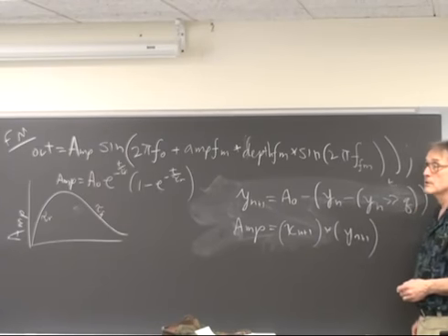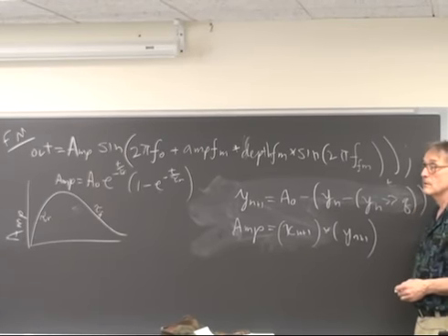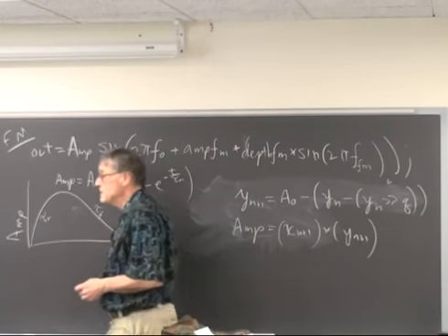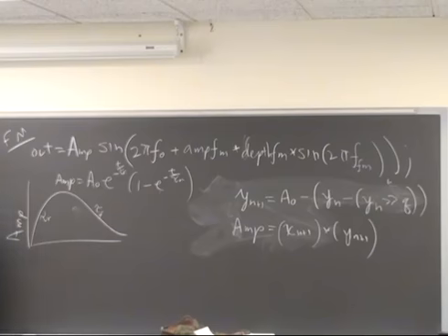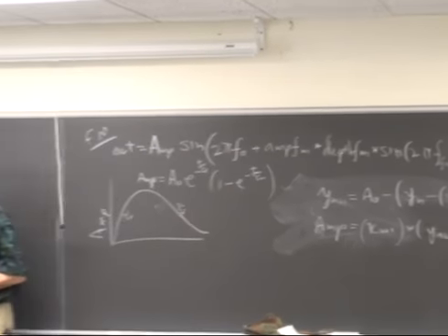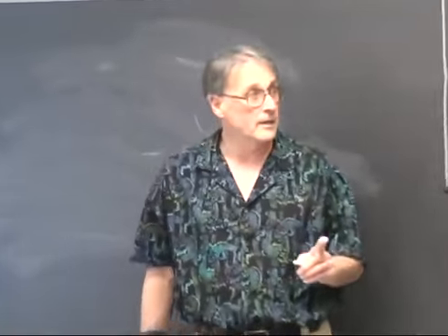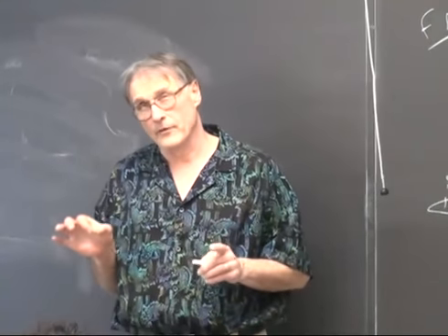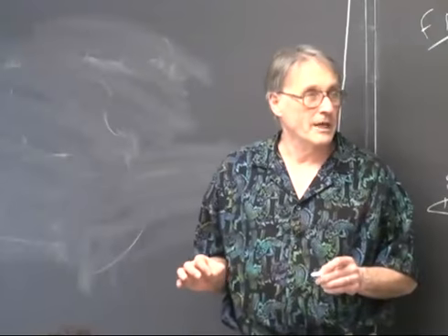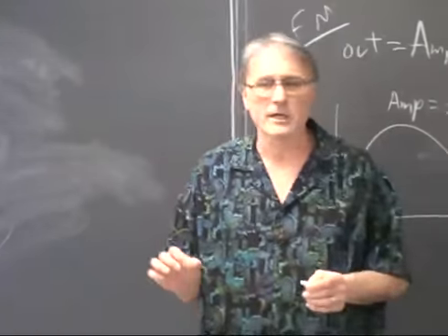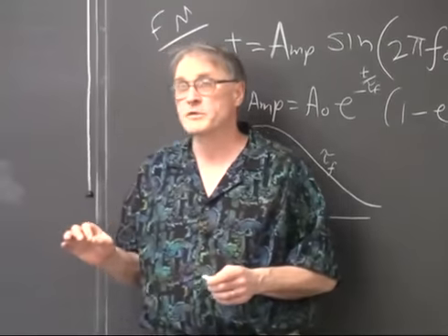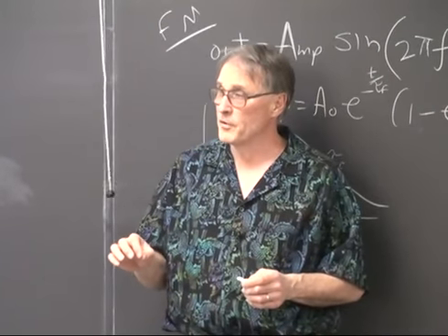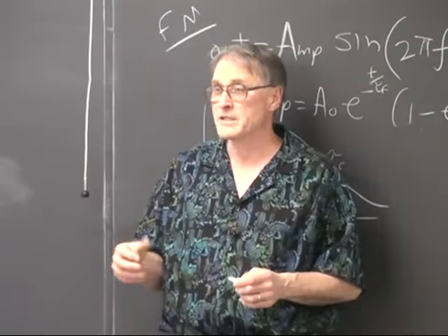Does this hinge on the fact that you're using such a low sample rate that you're not even going to perceive the differences in precision? It hinges on the fact that 256 voltage levels is pretty good. Now, I got to tell you that these various approximations do have a tendency, unless you're really careful with the round off, which I wasn't, to make a very low background whine about 25 dB below full volume.